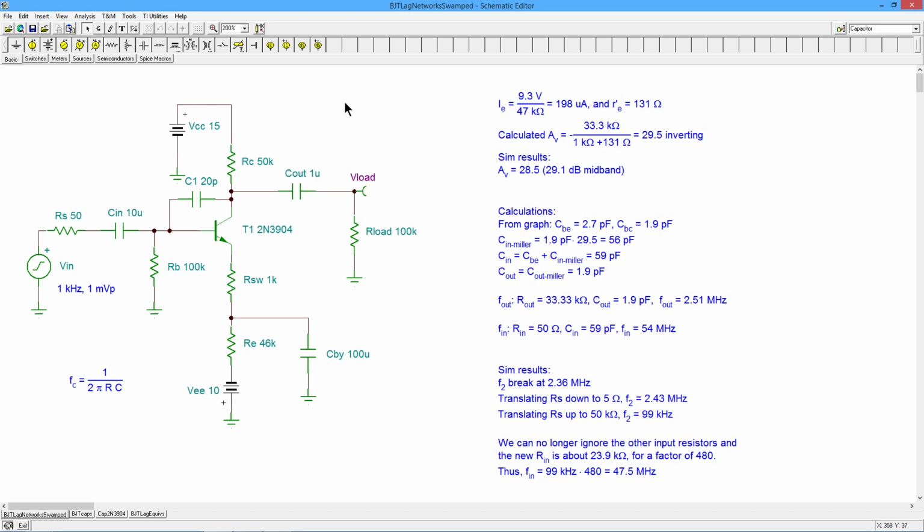Okay, so to recap, when we look at the high frequency response, it is primarily these little capacitance values, parasitic capacitance that exist around the transistor. In the real world, there are also some small capacitances associated with your resistors and wiring and so forth. So we come up with a couple of lag networks, one on the input, one on the output. It's sort of the mirror image of the lead network response. It's the lower of the two that's going to dominate the response. You can very easily, by adding a capacitor in the Miller position, decrease the frequency response, decrease the F2, limit the bandwidth.